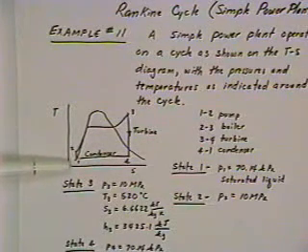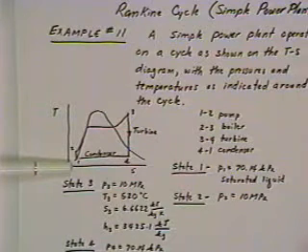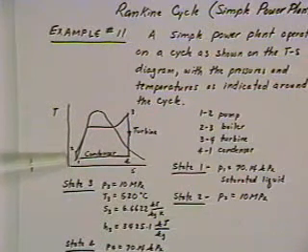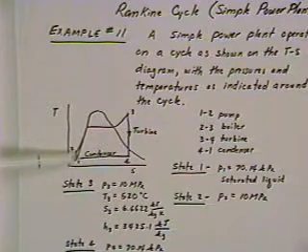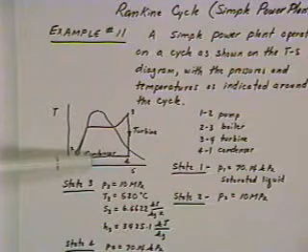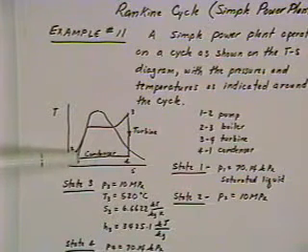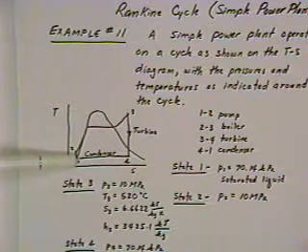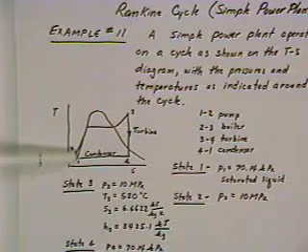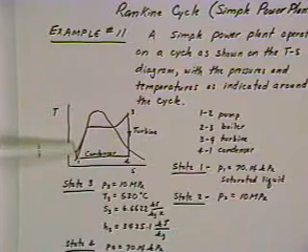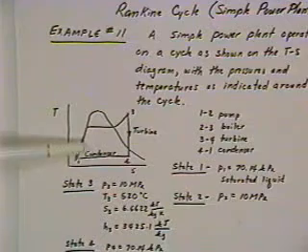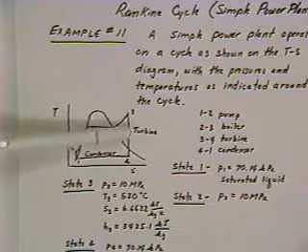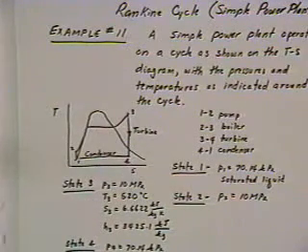Now, what we did on that little problem where we did the mixing problem, we put in an intermediate stage between the condenser and the pump where we heated the liquid water up to a little bit higher condition in order to have a more efficient, higher energy value of the liquid entering the boiler. But in this particular case, we're not going to assume anything except 4 very simple components: a boiler, a condenser, a pump, and a turbine. So this is our simple power plant cycle.